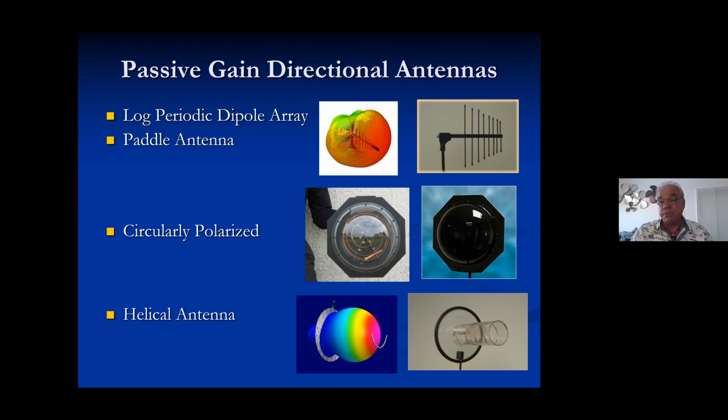And for you in-ear monitor folks out there, guess what? Those of you who have worked with me know I always try to implement the use of that second middle antenna, which is a CP, circularly polarized, not a helical. The reason is that the CP antenna has a much wider polar pattern, and you only have one transmitter, whereas the helical has a much tighter pattern like a spotlight, but because of diversity receivers, you can place a couple around to make up for your dropout zones.